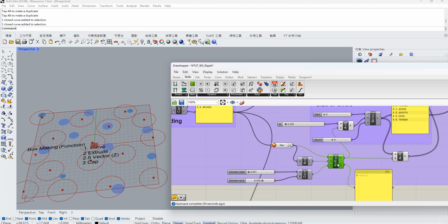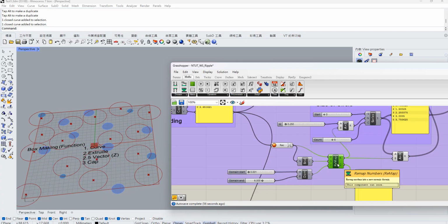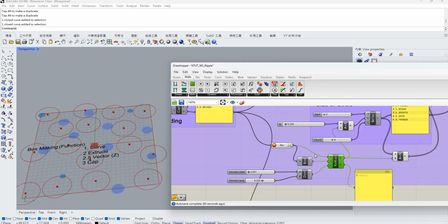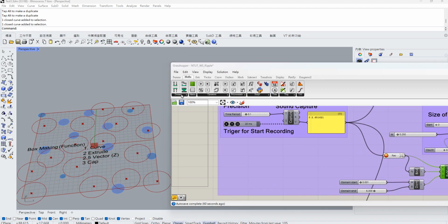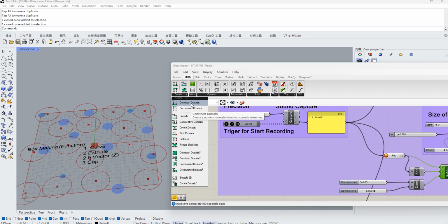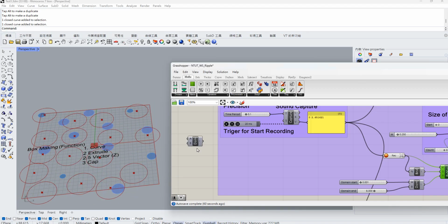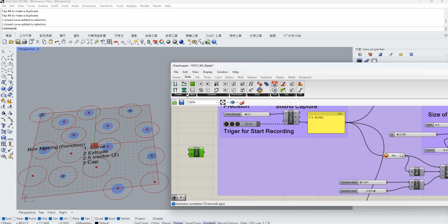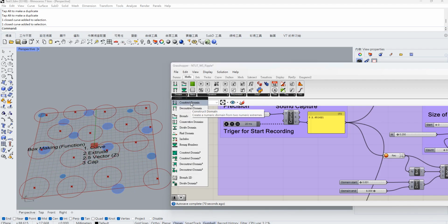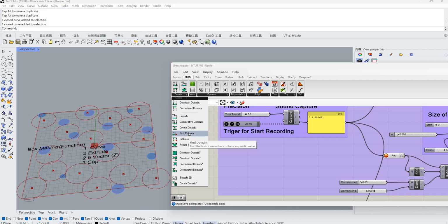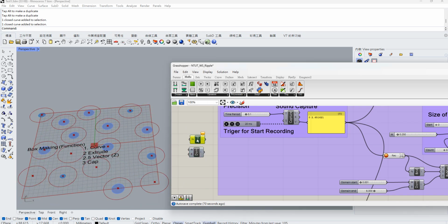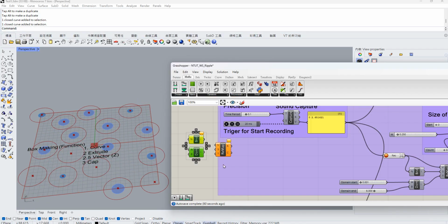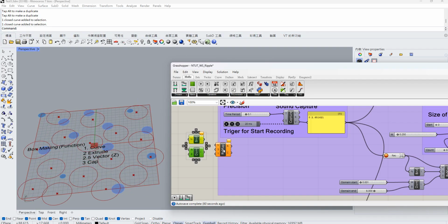Let's code out the components, put them on the canvas first, then we will explain the idea inside. So first, please give me this one, Construct Domain. This is the first one we are going to use, right here under Math, Construct Domain. Second one, Bounds. And the final one, Remap. So those are the three components we are going to use.